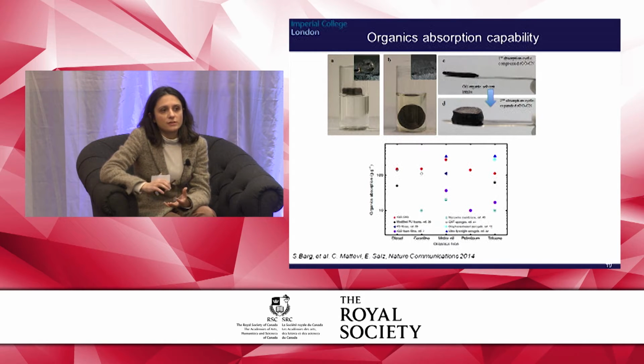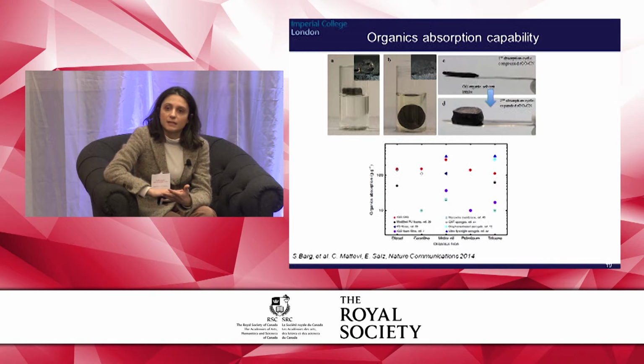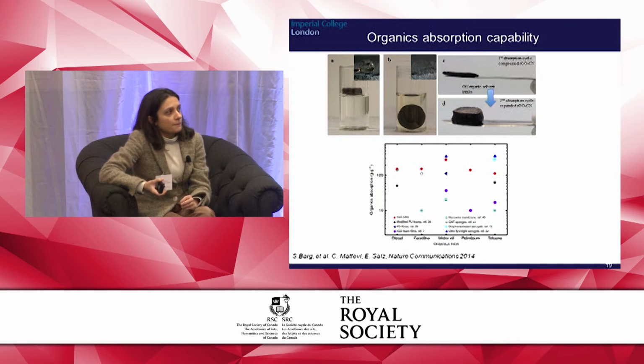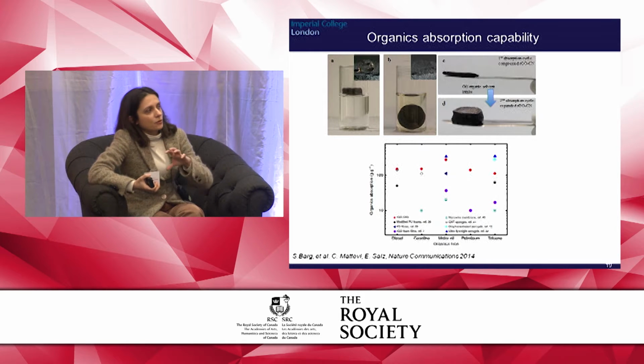So one of these constructs has overall viscoelastic properties, so that we can mechanically compress it, and then while releasing the mechanical compression, this material can retain exactly the same shape. And on top of that, the material is highly hydrophobic. So as we can see, the immersion of this material in an emulsion of water and oil will allow the preferential absorbance of the oil part of this suspension by the three-dimensional graphene construct.